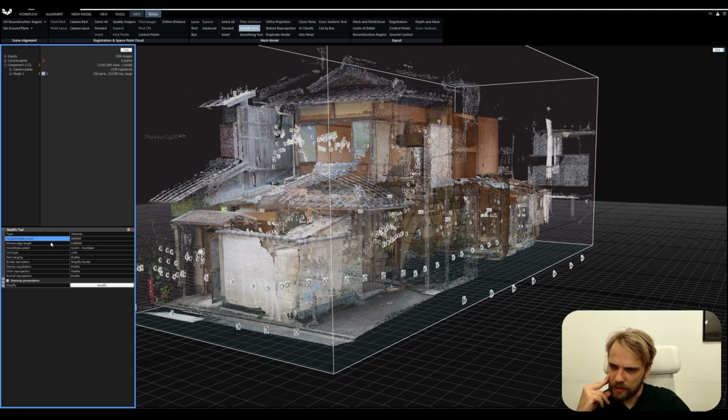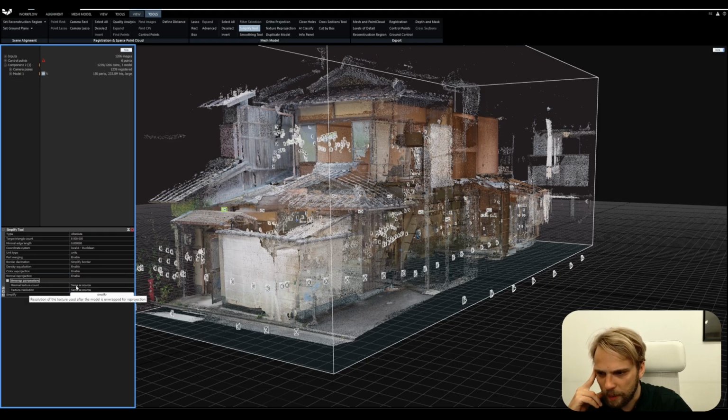Okay, what's next? Minimal edge length, that's whatever. Density equalization, we have it enabled. Color reprojection, normal reprojection. I'm actually going to also enable color reprojection because I haven't been using this before, but it seems like the texture is going to be reprojected on top of the simplified mesh. And let's check the parameters. Same as source for unwrap. That's excellent. Yeah, let's simplify it.